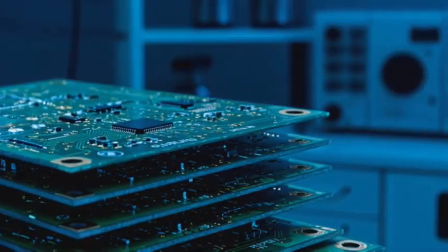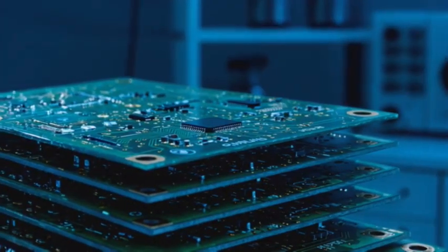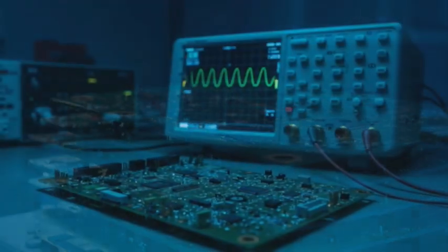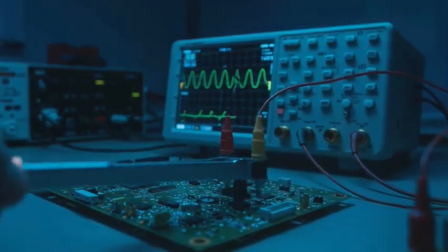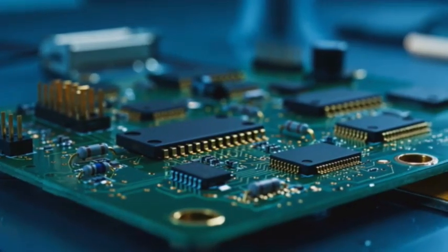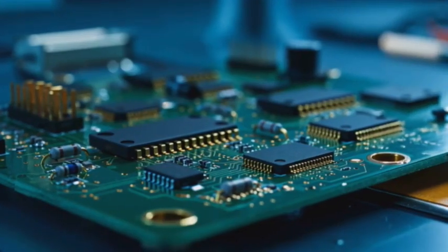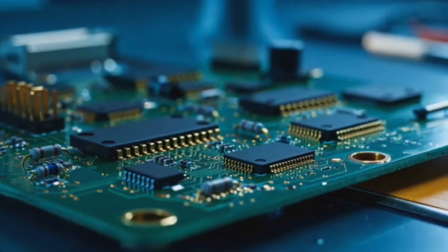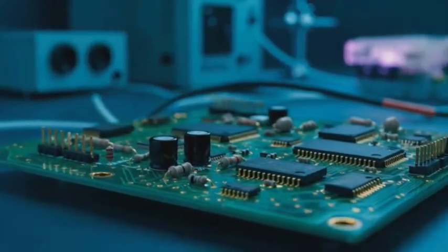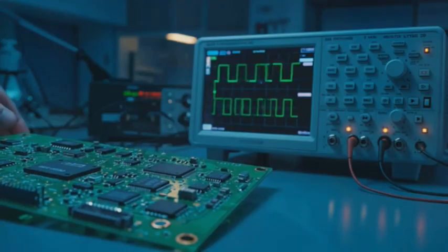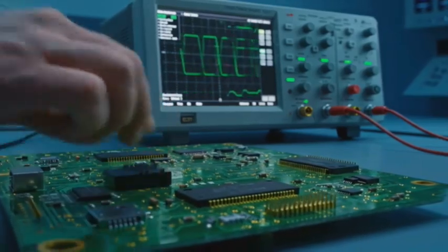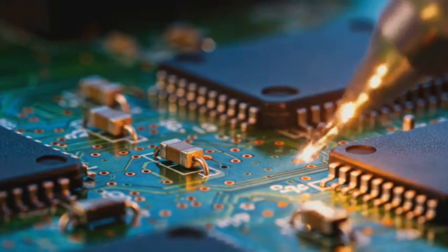To reduce EMI, always use solid ground planes, minimize loop areas, and route high-speed signals over continuous reference planes. Keep traces short and direct, separate analog and digital sections, and avoid running high-speed traces near sensitive analog lines. Decouple power at every IC with capacitors close to the pins, and use controlled impedance traces for critical signals.